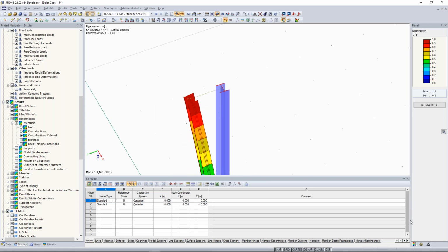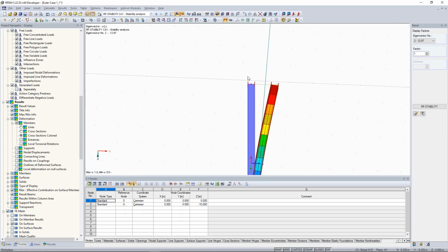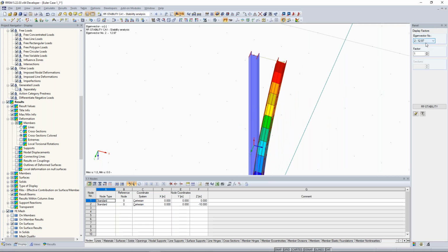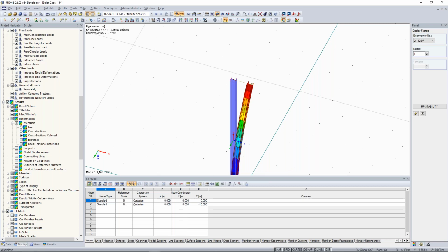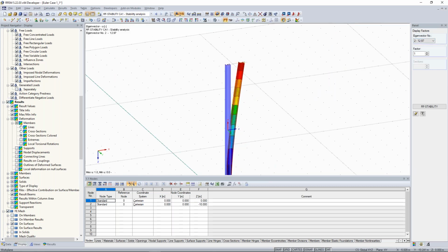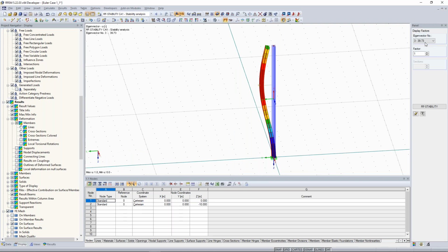When we jump to the next eigenvector, the second, this is a buckling around its strong axis. I think that's pretty clear. Here I have my flanges. This is the strong side. And here I have a critical load factor of almost 13. This would mean that if I multiply my 100 kilonewton with almost 13, then this would collapse around its strong axis. And there are also some other eigenforms and so on.